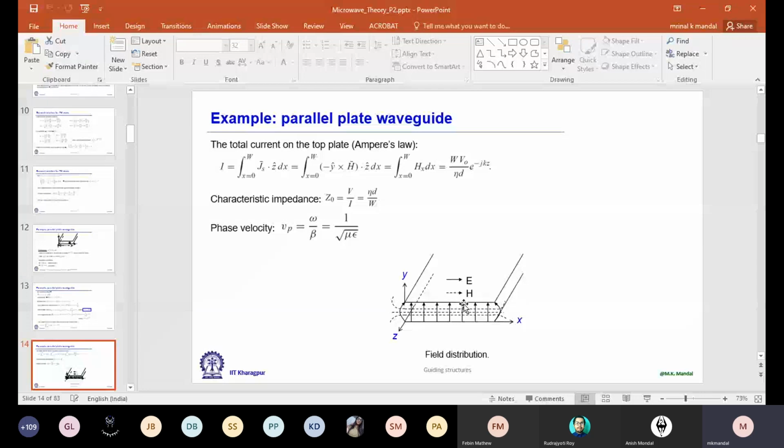So if I use that, then we'll see that just on the edge, and after that, this field component bends, as I have seen here, and magnetic field forms a loop. From here it goes up, then comes back here. So magnetic field forms a loop surrounding a plate, and this is in TEM mode. We don't have any component of HZ or EZ.